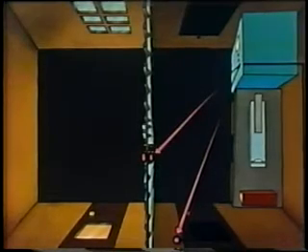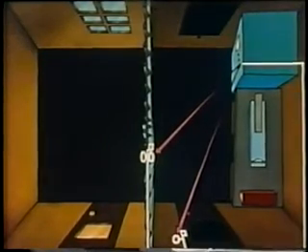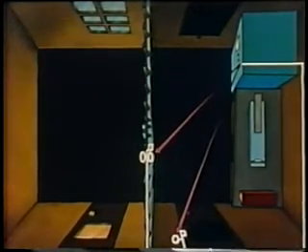Safety interlocks should be provided for all doors, the primary entrance and the secondary entrance, such as the isolating screen. The interlocks are connected to the power supply. When the power supply is turned on, the interlock switches lock the doors so that no one can enter during laser operation except in emergencies. The lock should not prevent quick exit from the room.